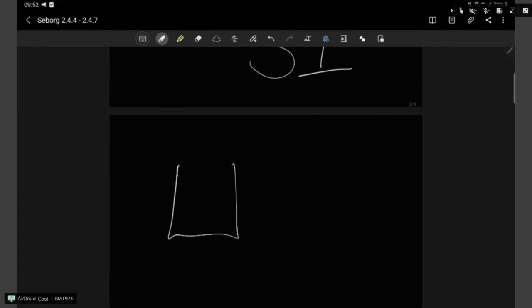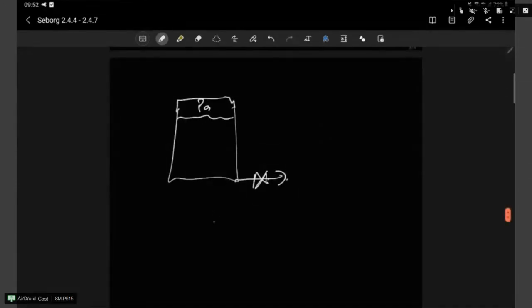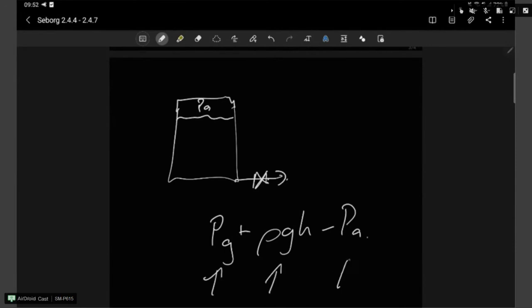So whenever we have this sort of scenario, and you end up with this form of the equation, something like that, always just ensure that these units are consistent, because this is a force balance, and you need to ensure that the newtons are related to newtons and that you don't work with megapascals or kilopascals or a mix of the stuff. Just always remember what the units of rho GH are. Okay, so please remember that.